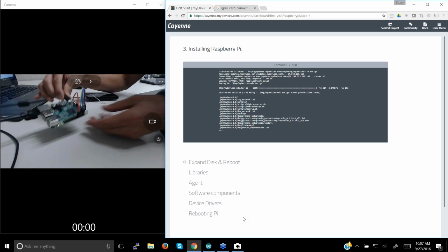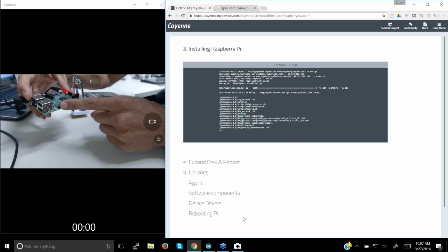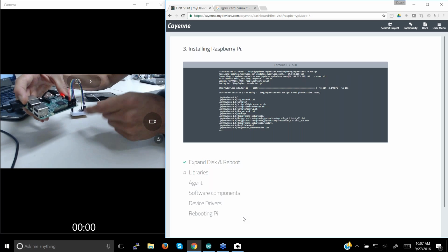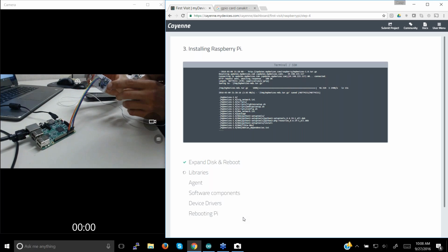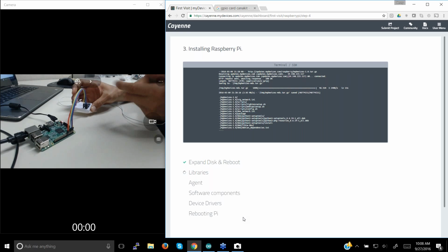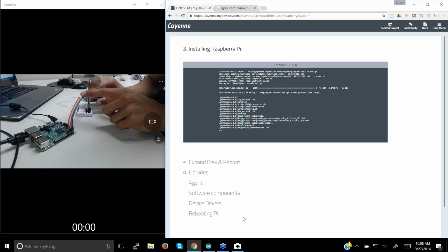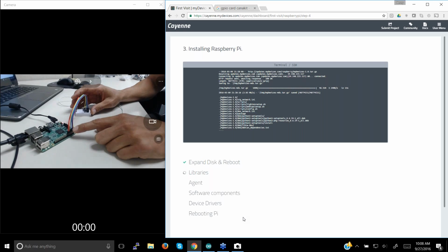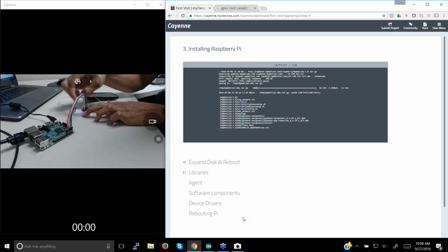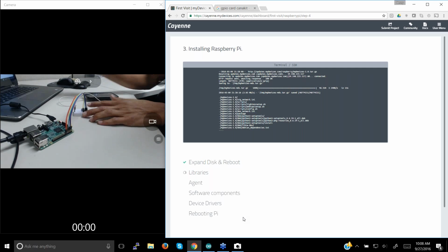Now, one thing I would like to go over at this point is the wiring. For those of you who are not familiar with the Raspberry Pi, this part right here is called the general purpose input-output ports. And this is the way that the Pi's sensors, such as this BMP180 and this LED, connect to the Pi and send data. The BMP180 is basically going through these wires, sending data to what are called I2C ports on the Raspberry Pi, and then the LED is just picking a general port that's connected to the Pi here.